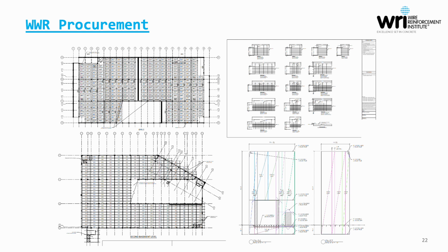Here are a few illustrations. These are actually snippets from actual shop drawing submittals. You can see these are building footprints over on the left side, showing the arrangement of the different mats that comprise the elevated slabs. And then over on the upper right, you see the actual illustrations of the actual mat designations that are called out on plans. So again, when you get into structural material, the main takeaway is that it's going to be a highly illustrative shop drawing submittal for review by the designer of record as well as the contractor.